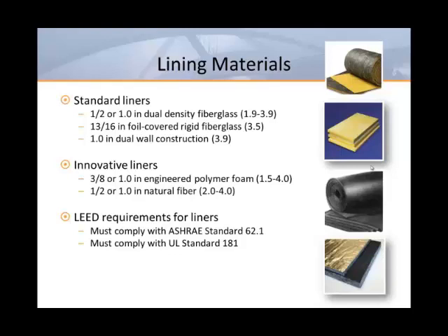It's important to keep in mind that the lining material choice could have either a positive or negative impact on the acoustical performance of various types of terminal units. As a general rule, the harder the facing is on a liner, the less sound it will absorb. This can increase the transmission loss through the casing, resulting in lower radiated sound levels, but it can also result in higher discharge sound levels. Softer linings are not as effective for blocking noise, but can provide somewhat lower discharge sound levels.